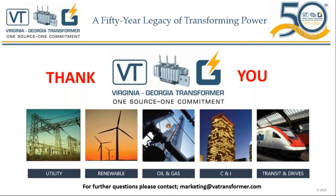So if you see a lot of hydrogen, then you may think there's a PD. If you see ethane, ethylene, methane, so there's actually very good literature on understanding the DGA results available online.